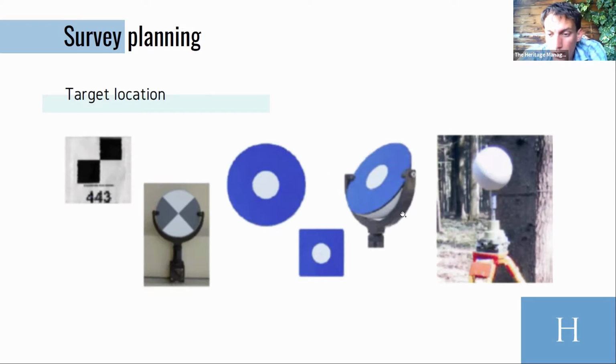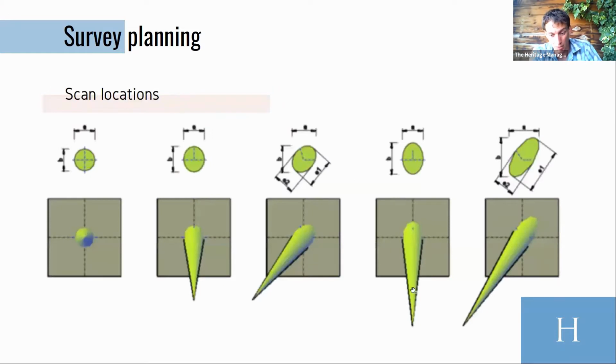They all have advantages and disadvantages. In general, I would say that this is the most accurate way of defining your coordinates, because it is based on geometrical measurements. And another big advantage is that if you have a scan from one position and a scan from another position, in this case you don't have to rotate your target. You're just measuring the surface of the sphere, and the point is extracted or calculated in a systematic, coherent way. But in the other case, you will have to rotate your target in the direction of your scanner because of this phenomenon.